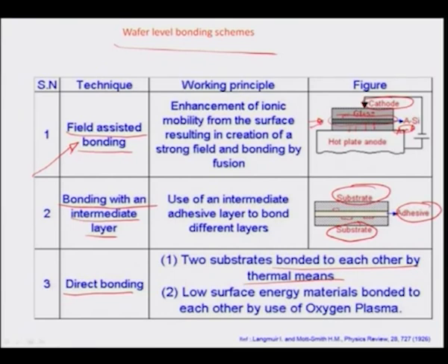And in the other illustration, particularly in the polymer MEMS case, you can lower the surface energy of the material by exposure to a variety of plasmas like argon plasma, oxygen plasma, and so on. So, once the surface energy of the material is lowered and it is made more hydrophilic, there is automatic adsorption of OH or hydroxyl groups on the surface, and the hydroxyl groups would polycondense together to formulate a bond of irreversible kind between the different exposed layers of polymers.